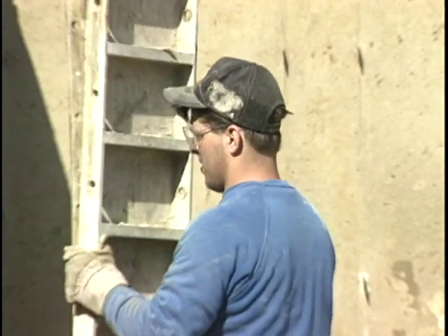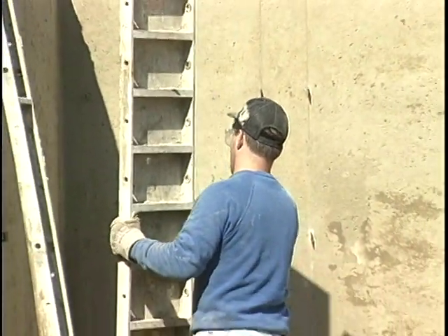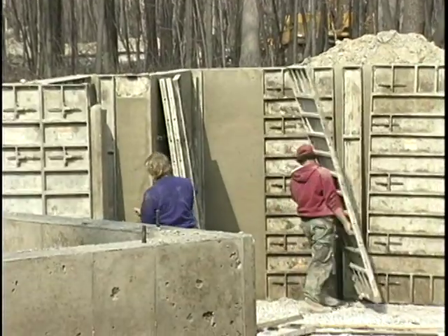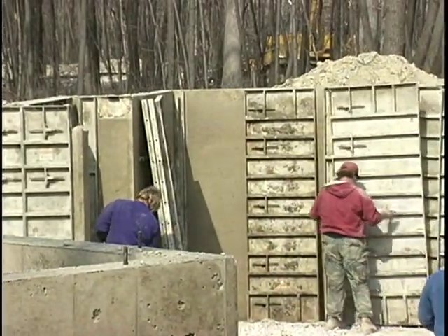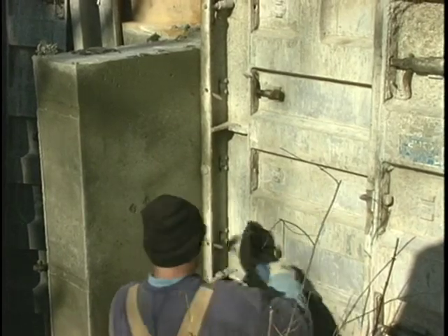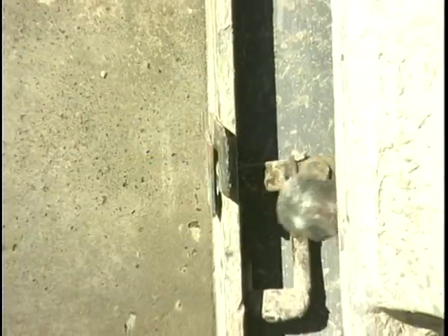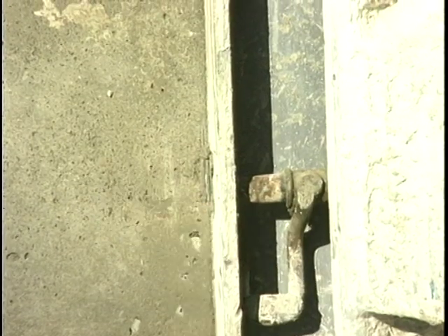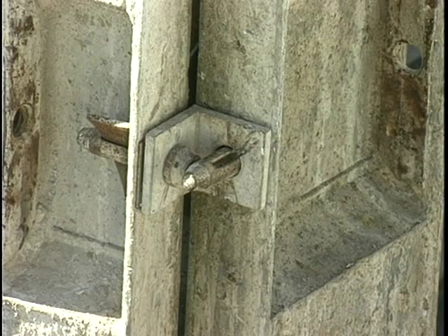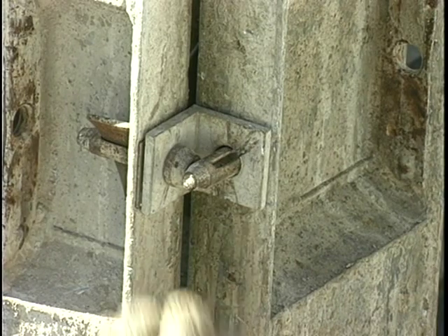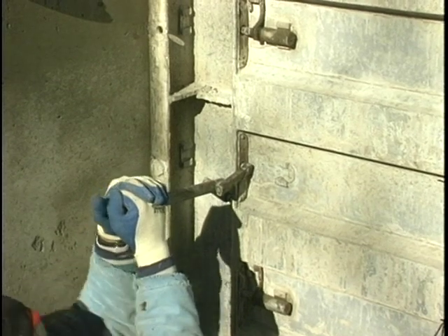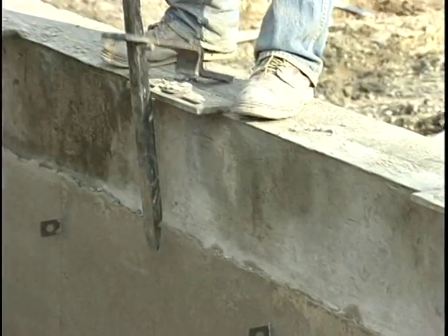Wall forms help protect concrete from drying too fast. They should not be removed until the concrete is strong enough to carry the loads that will be placed on it. After the concrete has had enough time to harden, the clamps can be loosened and the forms stripped away. Hammer blows are used to remove the clamps, pins, and metal wedges. A special pry bar is often used to force the forms away from the concrete wall.